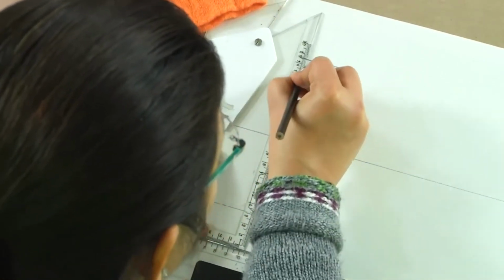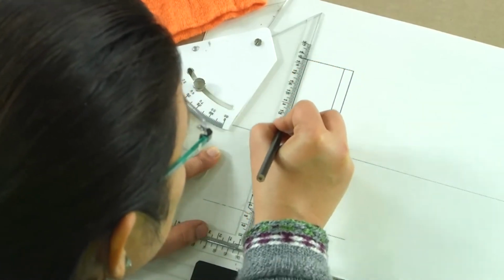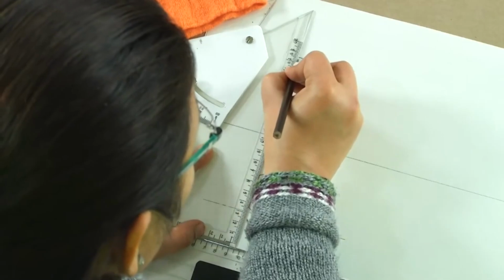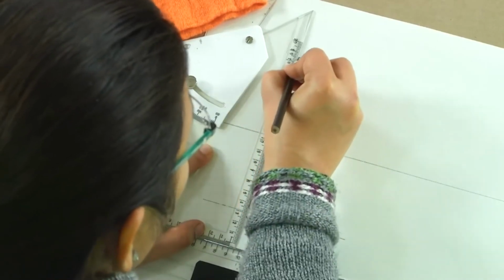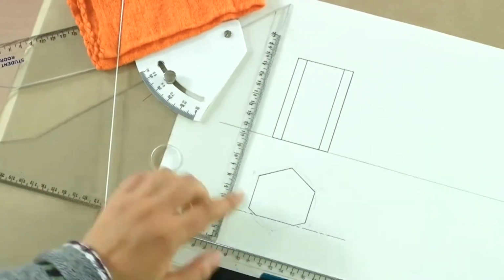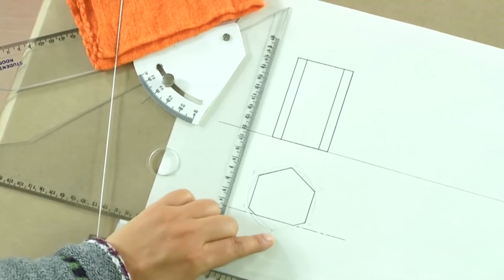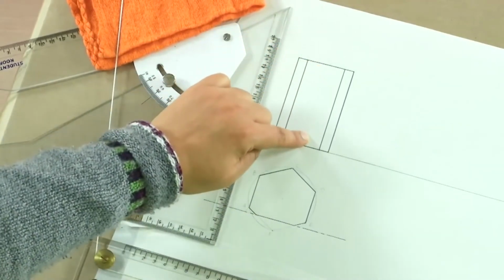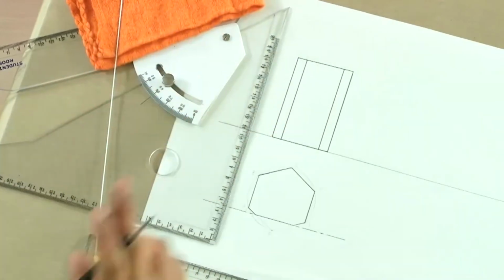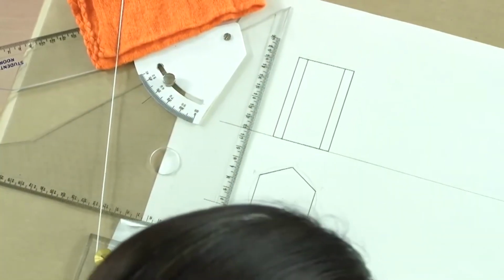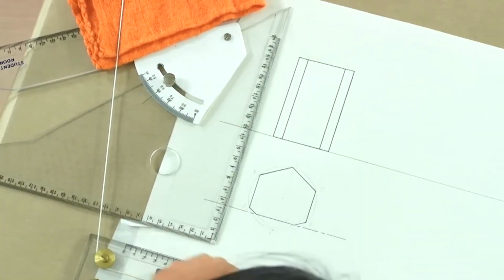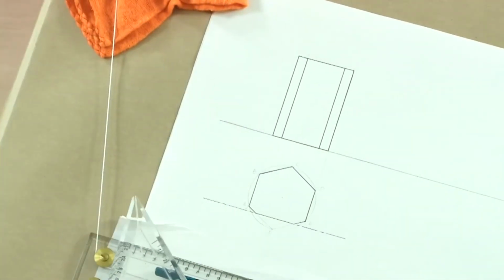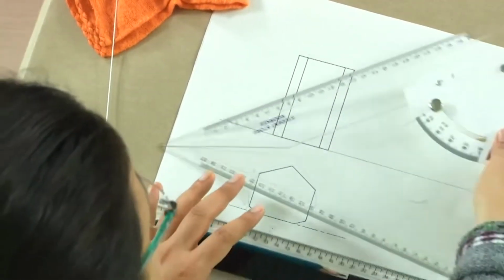Now, the middle edge which we were originally seeing initially when the prism was assumed to be kept, this edge which is F, starting from F, that edge has totally gone. So, we do not see any edge like that there anymore, and what we have to do is to mark that this is a cut edge, because this is what we are seeing.